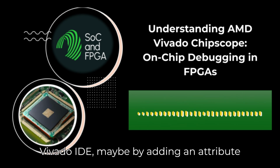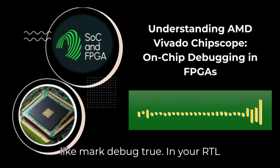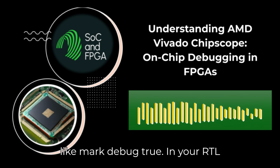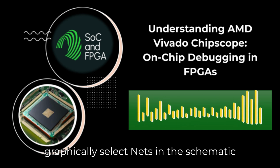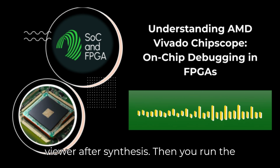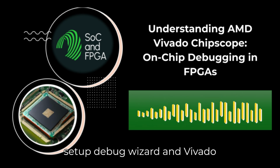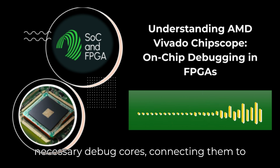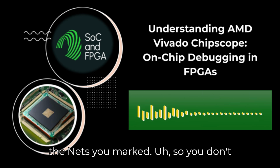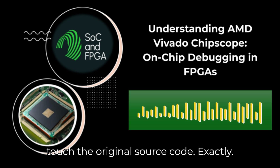You can do this in the Vivado IDE, maybe by adding an attribute like mark debug true in your RTL beforehand. Or you can just graphically select nets in the schematic viewer after synthesis. Then you run the setup debug wizard, and Vivado automatically creates and inserts the necessary debug cores, connecting them to the nets you marked. So you don't touch the original source code.